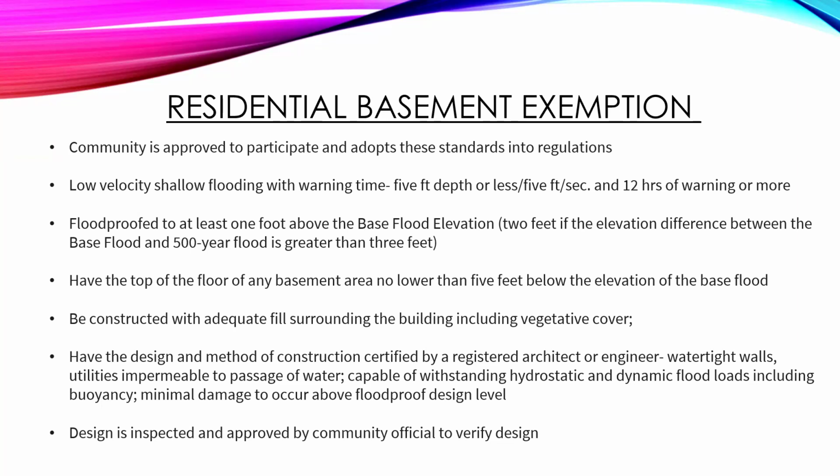Adequate fill surrounding the building. And then it also has to have a design that's certified by an engineer or an architect. Watertight walls, utilities that are impermeable, capable of withstanding the flood loads on the building. That includes buoyancy. Minimal damage to occur above the floodproof design level. And then this is inspected by the community official to verify that.